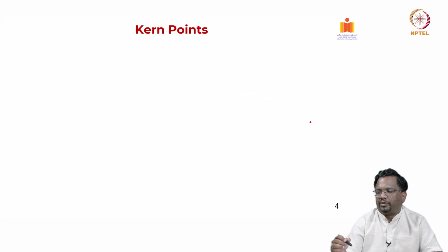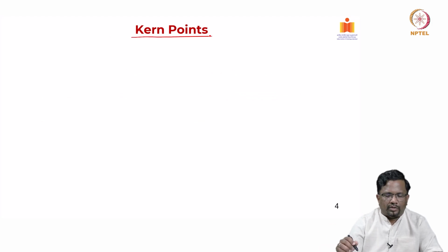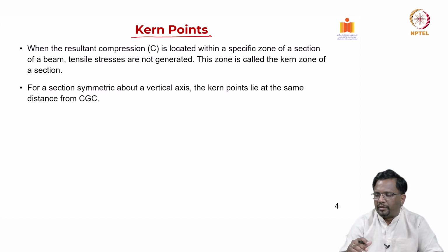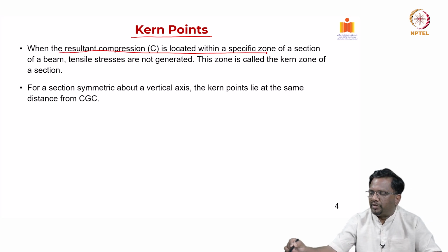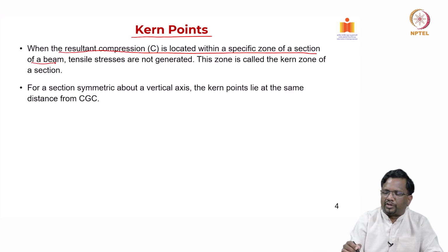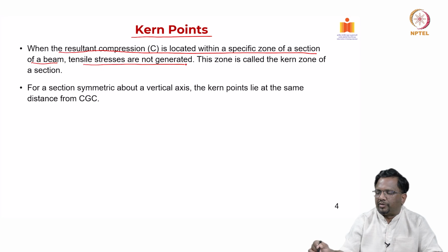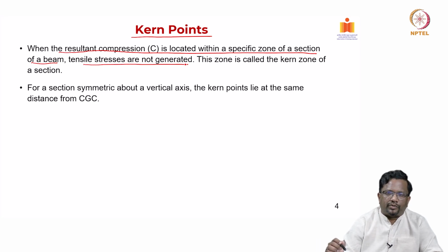Okay. So, Kern point. Some of you might have learned this when you did the foundation design, there is a Kern zone, right. Similar to that, here in pre-stressed concrete sections also, when the resultant compression is within a specific zone of a section, the tensile stresses are not generated. This zone is called the Kern zone of a section.